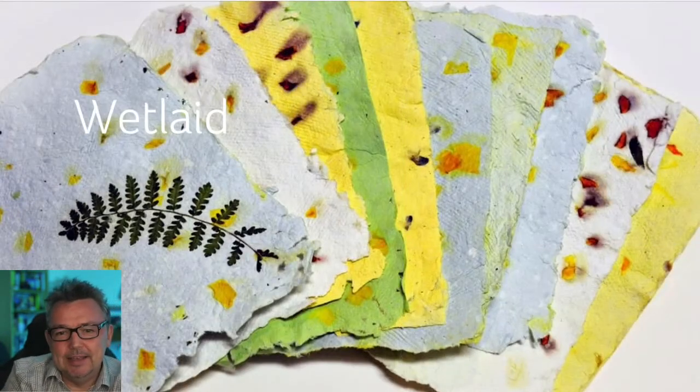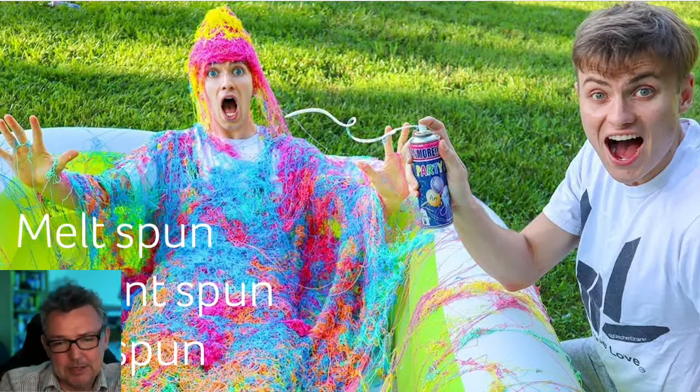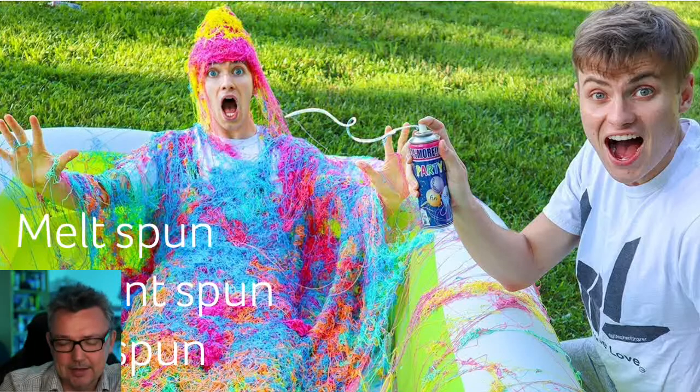Then we have wet laid, and wet laid essentially is very similar to making paper. You suspend lots of short fibres in some water, drop it down onto a mesh screen, and then you produce a web of fibres, and that's known as wet laid. Then you have melt spun, solvent spun, and wet spun. For melt spun, you take thermoplastic fibres, which are basically polymers that melt, squeeze them out of very small dies, put them into jets of air. They stretch out to become very fine fibres, and they can be deposited onto a belt.